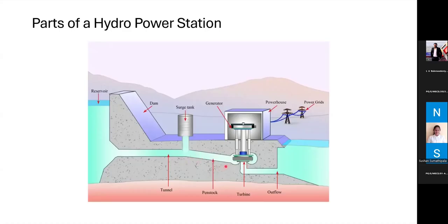A penstock is a metal tube that can withstand high pressures, and the tunnel could be a concrete reinforced tunnel or a tunnel going through natural stone in the geographic terrain. Because the tunnel is a horizontal structure, it doesn't have higher pressure, and it's normally a low pressure channel of hydro conduction, and the penstock is the element that withstands the high pressure of the water.